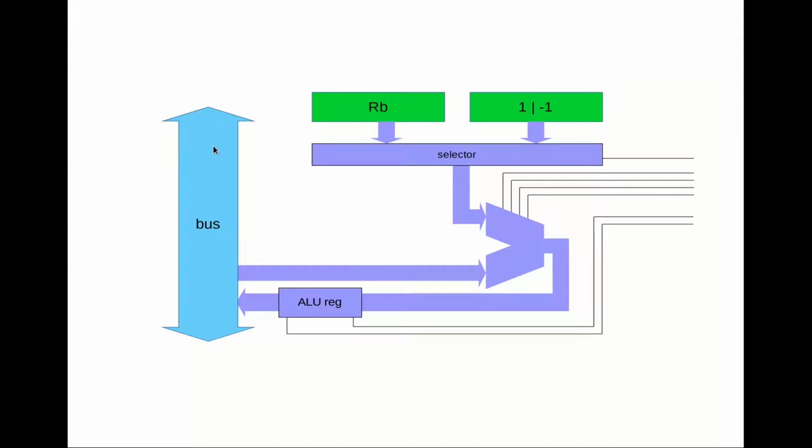And so we see that because we are using the bus for both the input into the ALU and also the output from the ALU, we actually need two micro clock ticks to perform an ALU operation. And in the first one, the first operand will be on the bus, and on the second clock cycle, the result of the calculation will be out on the bus. And that's really the only way to do it, by using a single bus, as we have in our computer.